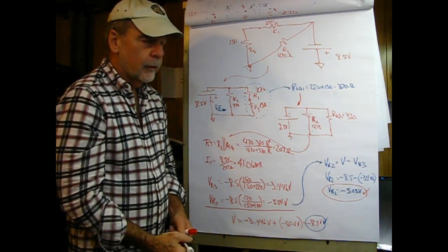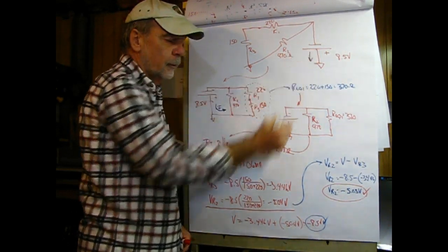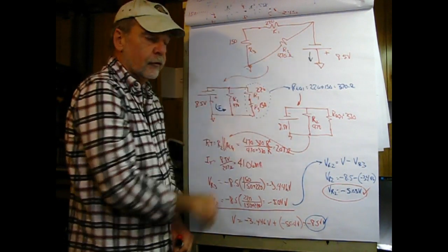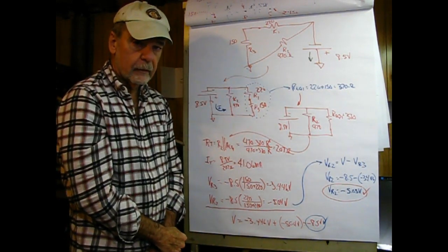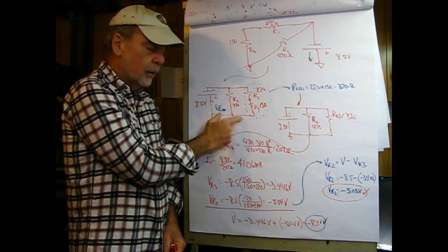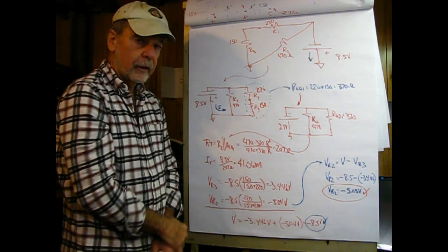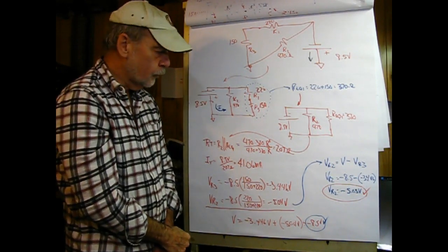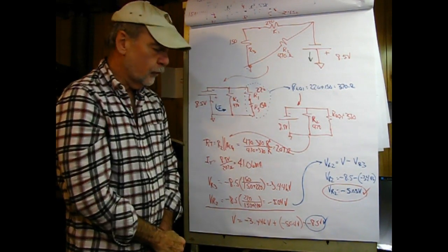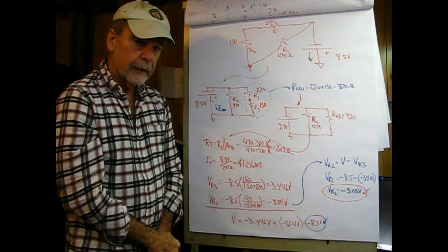The important point to see here is that the current flow out of the source is going to be toward ground. Now, you can solve this as it's drawn if you're comfortable with the diagram. If not, convert it into a standard form. Move the source over to the left, combine R1 and R3 that are obviously in series, and put these two resistors in parallel with the 470K. So this would be the conventional way of drawing that circuit.